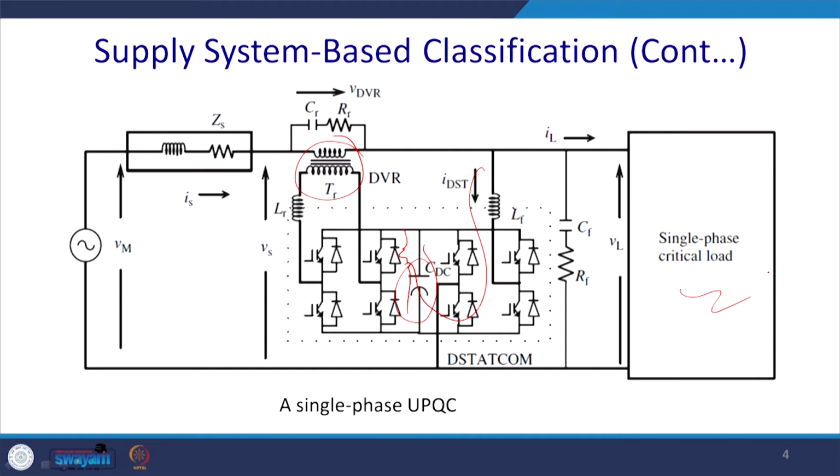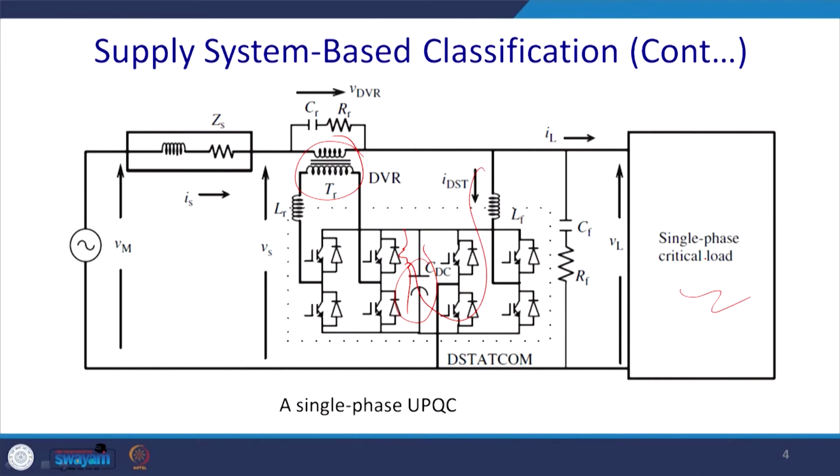This is the single phase UPQC solution, mostly it comes with single phase adjustable speed applications. For example, you may have lifts, because nowadays we want the movability of the disabled everywhere. So, we want the lift, and maybe in an old building that does not have proper grounding and lift. So, we have different kinds of 1 man, 2 man lifts, and that rating can be up to maybe 3 kilowatt.